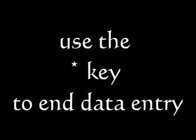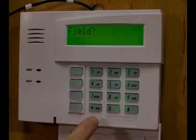Oh yeah, I did figure out a shortcut while you're programming if you're only doing one partition. Just enter your partition 1 variable, then hit the asterisk key. Watch while I program exit delay to 0. Let's set it to 0.